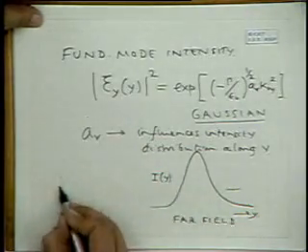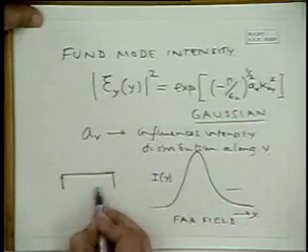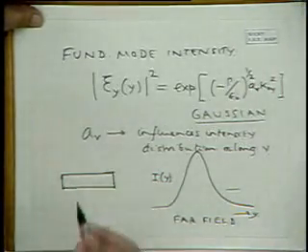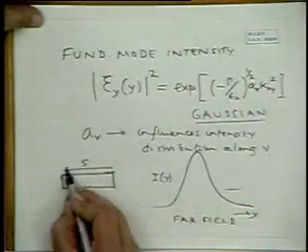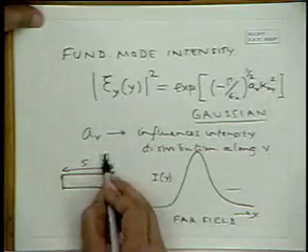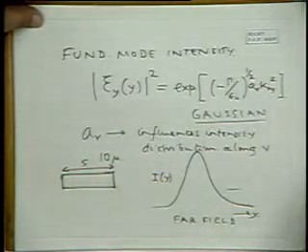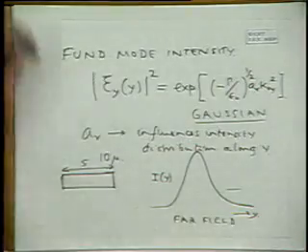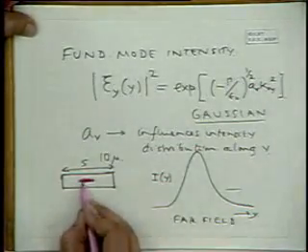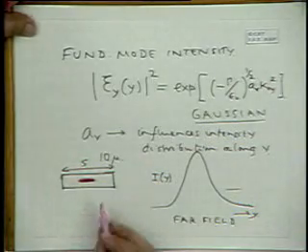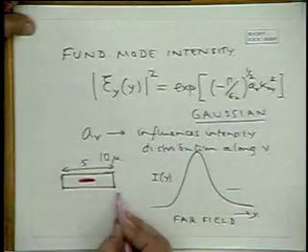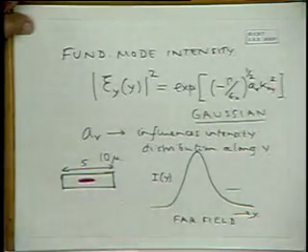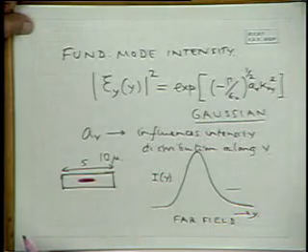And if you look at the actual aperture, this is the aperture through which the light is coming out perpendicularly. Okay, this S is 10 microns. If this is 10 microns, then what you'll find in the case of a single mode, there'll be a single maximum here, which is characteristic of a single mode. This is the maximum intensity, and the intensity will decrease. And this is what you want for the fundamental mode of operation.